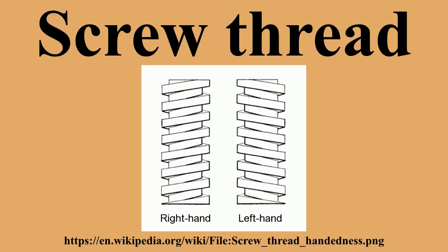The minimum limits for internal and maximum limits for external threads ensure that the threads fit together. Major diameter. The major diameter of threads is the larger of two extreme diameters delimiting the height of the thread profile, as a cross-sectional view is taken in a plane containing the axis of the threads. For a screw, this is its outside diameter. The major diameter of a nut may not be directly measured, but it may be tested with go/no-go gauges.